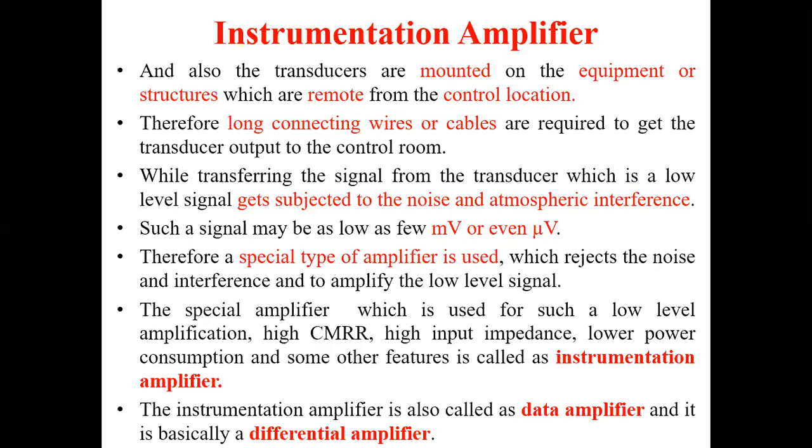Therefore, we have to reject these noises, and at the same time the small signal has to be amplified. An ordinary differential amplifier cannot do this, and therefore a special type of amplifier, which is nothing but the instrumentation amplifier, is used in this case.